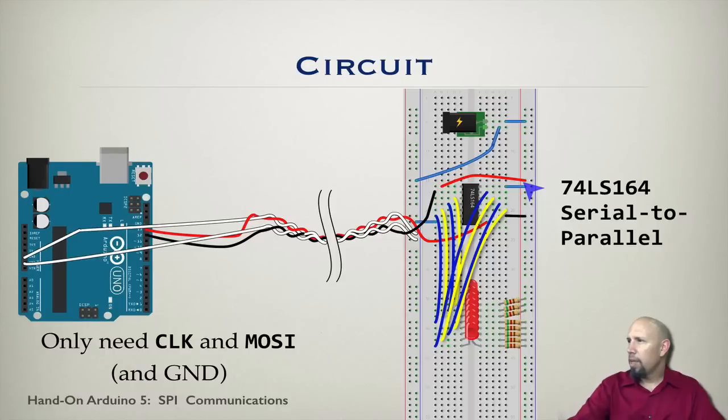Okay, so notice that this connection to 5 volts is on the chip connection called clear, and it's clear active low. So active low means that if I ground that connection, it will clear the outputs. So I don't want that. I want the outputs to remain to go out, and so I just pull it high. Okay, and then the other 8 connections.